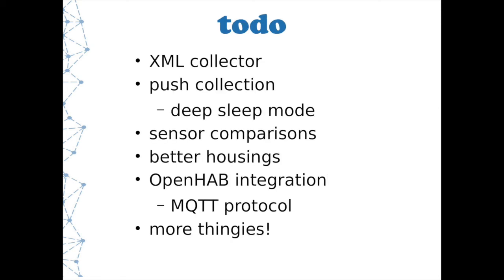I have a lot to do. I have other more efficient collection means for the energy efficiency of the device. You can do push collections from them, and by doing that you can bring it up quickly, send out a metric, and drop it into a deep sleep mode, and that'll extend battery use to like months, if not years. I don't have that set up yet, but that's one that I'm working on.